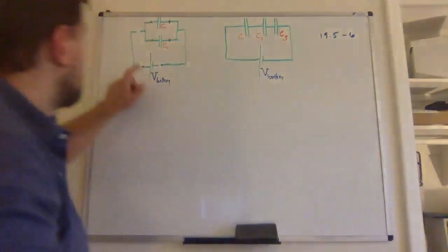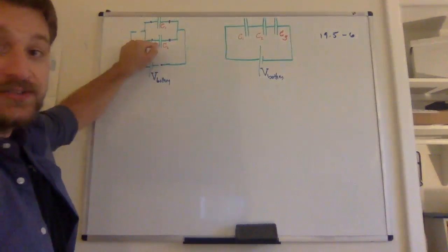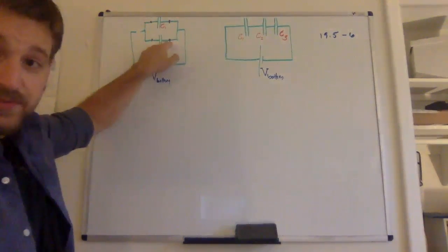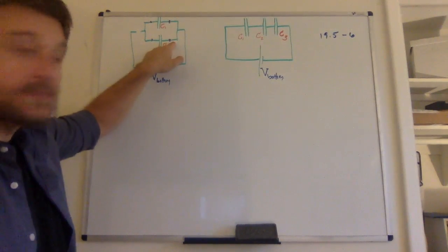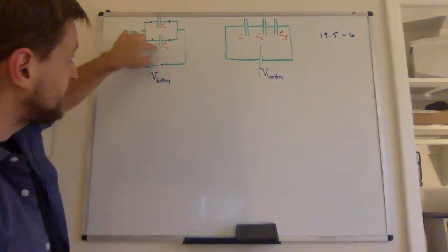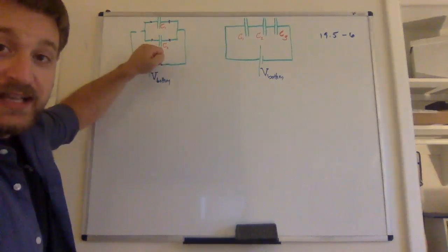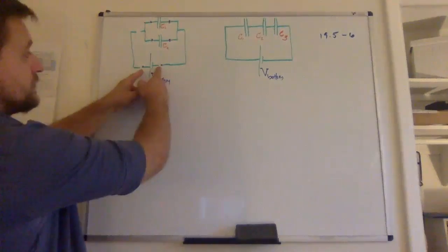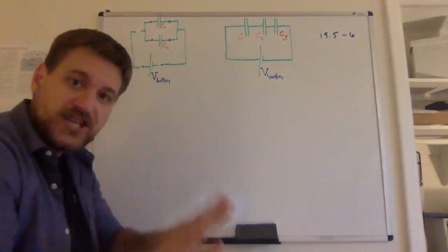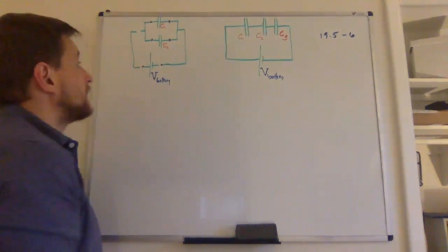Check it out. The battery wants to put positive charge here on this side of capacitor 2 by taking positive charge away from this side, leaving this side negative, just like the battery. So the left-hand side of this capacitor is going to be positive, and the right-hand side is going to be negative, just like the battery. We take our two voltmeter leads, move them from here to here, nothing changes. It's exactly the same potential difference.